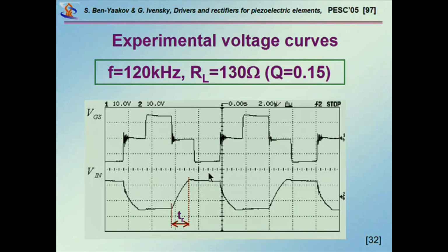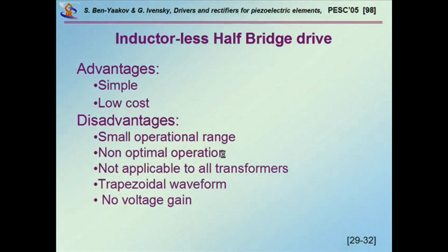While if the Q is smaller, then you have to go to a larger deviation of frequency. And this is probably what makes it a little bit more suitable for this. And as we know, some papers, Professor Lee's group, etc., show that with the radial they get a pretty good result. But there's no question that compared to the case in which you do not use this inductive mode, the efficiency will be higher. There's no question about that.